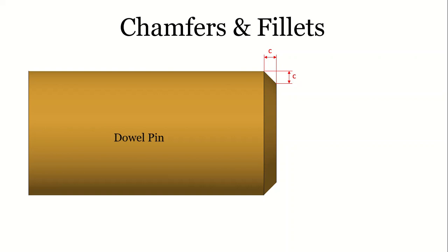I have designed one component for a hydraulic application where a plug has to go inside one hole, and that hole had one seal. When I was assembling the plug into that hole, because of the seal I was facing so much resistance. So I gave a 20 to 30 degree chamfer on the plug so that it slides inside. So there is no restriction on the angle, but it depends upon the application.